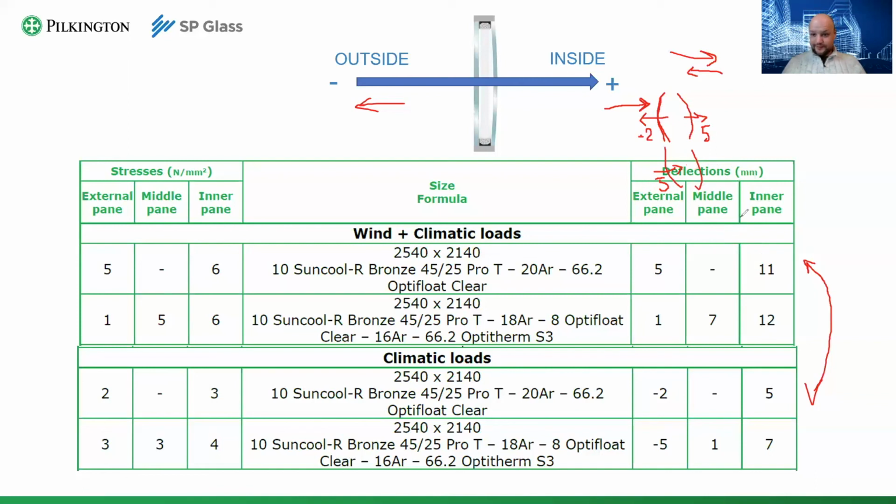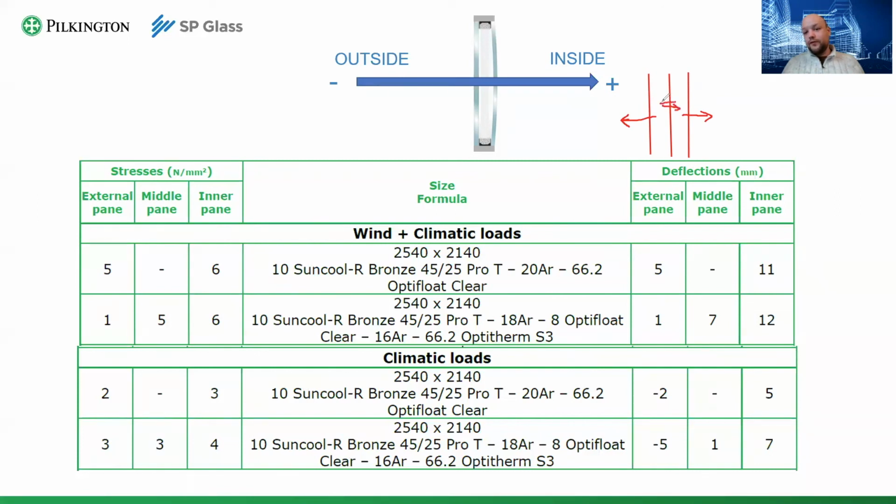Let's talk about triple IG unit. For a triple IG unit, the situation with the climate loads is not that good, because you have 3 glass. Can't paint it good enough with my mouse. So you have 3 glass, like this. Now, what are the climate loads? Expansion of both chambers, so here, here, and the middle pane, both forces are more or less equal. So the middle pane is under no stress. It is perfectly good because it's equally pressed from both sides.